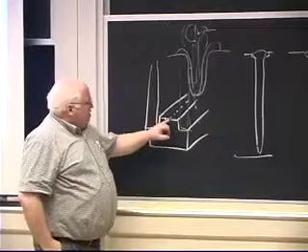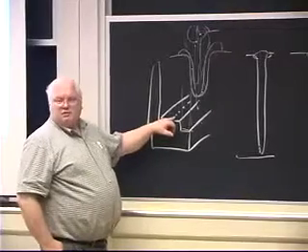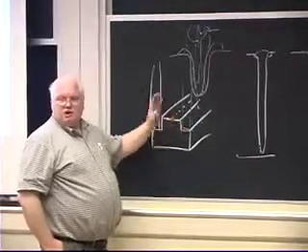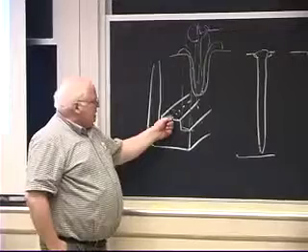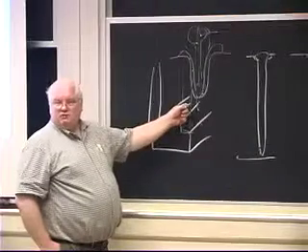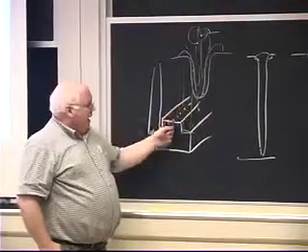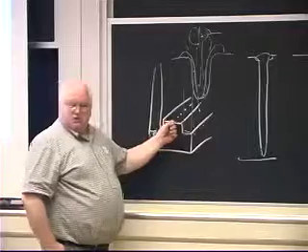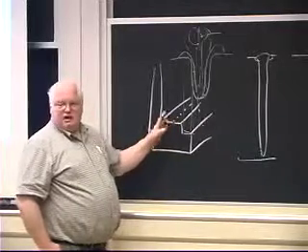But you don't want this to be a hermetic seal because atmospheric pressure changes back and forth. And so you actually want this to be an intermittent weld. And what happens is they actually do this mechanically now.